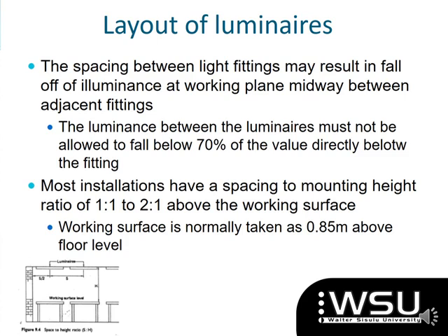So if you are indoors and you are just told 4 meters above ground, then you always need to remember that there's a 0.85 factor that you have to subtract, so that you always make sure we are talking from a working surface level or a bench level, as they would name it.